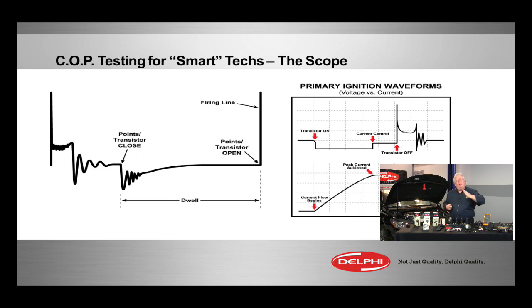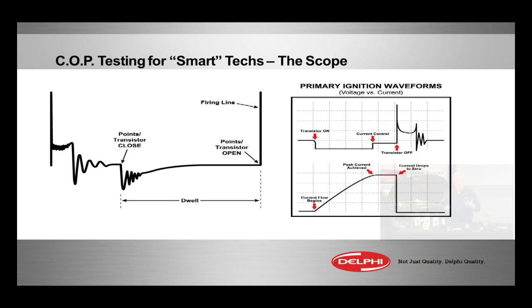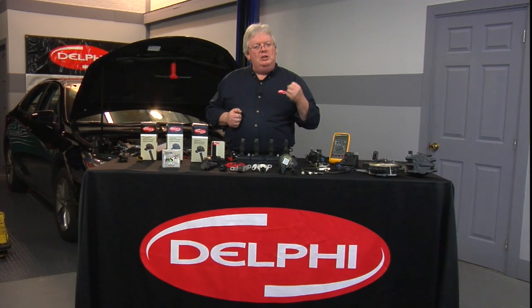But how that progresses, whether it shows a lot of turbulence due to air and fuel issues, or whether it does a steady rise and then at the end gets much steeper, that would be from a mixture running out of fuel, a lean mixture. So all those things mean something. If we had more time, we'd get into it. At a later date, we may do a whole scope class, but just keep in mind that you want to look at known good patterns, record them, go onto iATN and other sources like that to find patterns, and compare to what your customer's car has.